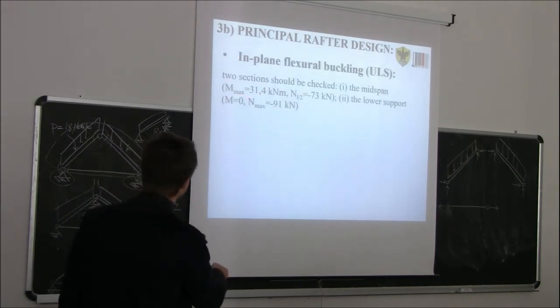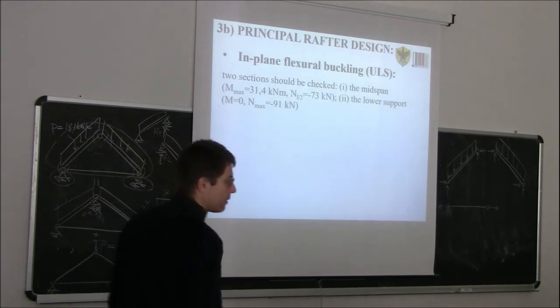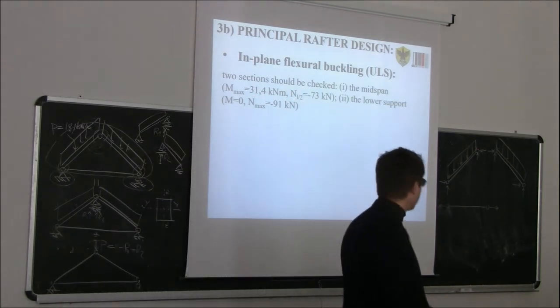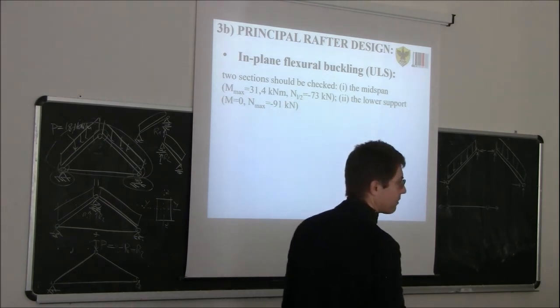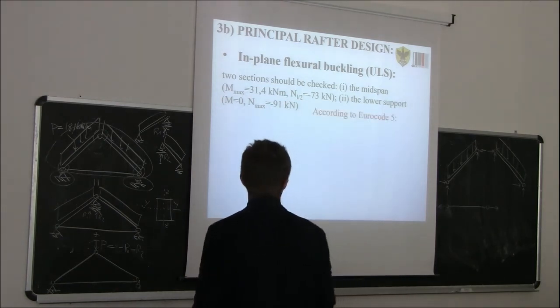So, mid-span, maximum bending moment and a high value of compression. Lower support, no bending moment, maximum axial force, compression.